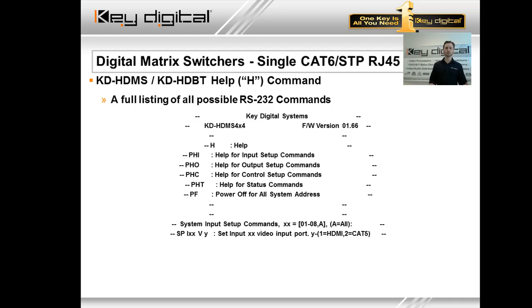Beautiful thing to do. You take your Blu-ray player, PC, set-top box, etc., and plug it into that HDMI port on that input 1. Guess what? You're not going to get so much as a sync light, a blue sync light, which should be active if we were selecting the HDMI port. Similarly, you plug your source into the balun, and connect that Cat6 shielded. Now you're going to get that blue sync light that locks in on the card slot.